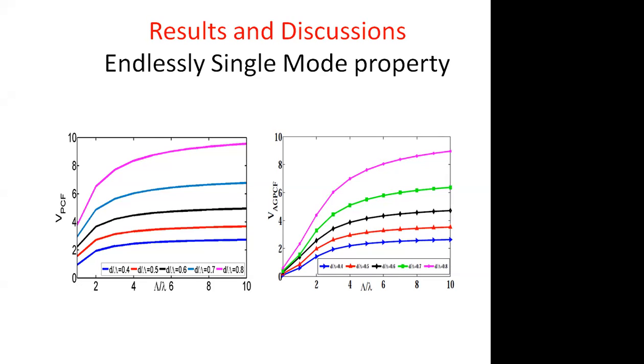Will you buy it? Probably out of 100, 1 or 2 may get it. The rest, they finalize on what? Cost, right? Similarly here also. You design a communication system, but its cost is more, right? Nobody will listen to you. They will say very good, but they say that cost is more. So if you increase core area from 12 to 36 micron, that means roughly you can pump 2 times more power into the fiber. So you can reduce the number of repeaters required.